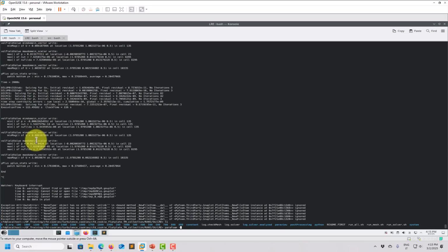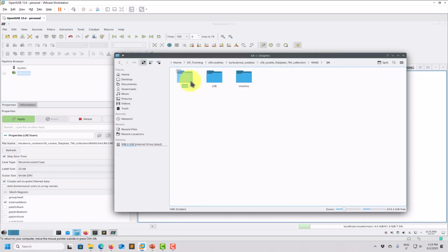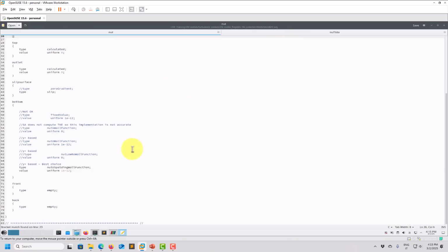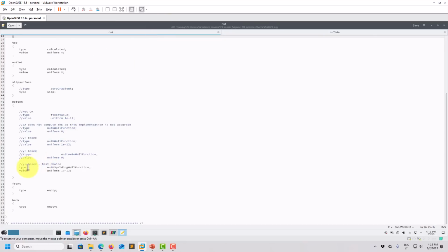Then let's do the post-processing, but before doing the post-processing, let me go here, move, low Re, and to stress something about this too. So nu tilde, nothing to do there. Okay, it's pretty much the same. Okay, nu tilde, put it here. So see, this will be pretty much the same definition, independent of whether it is wall modeling or wall resolving. Nut here now, look at that. I'm using the nut U Spalding, but you can also use the nut low Re wall function, or the nut U. All of these are going to work.